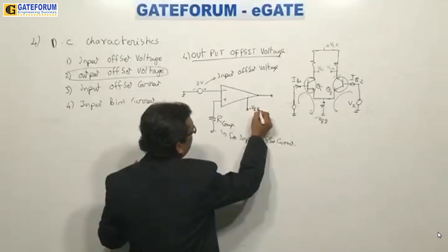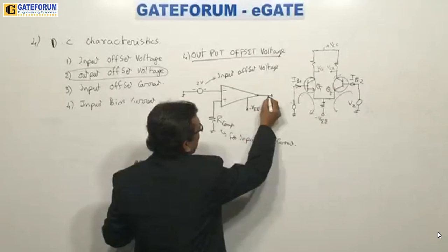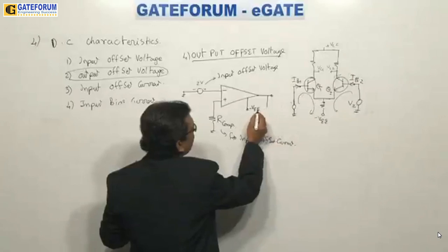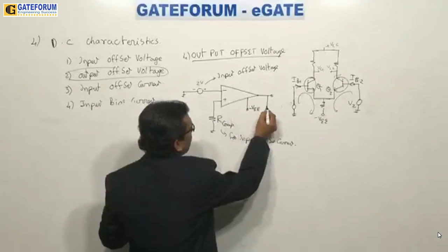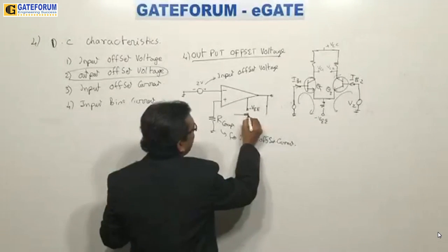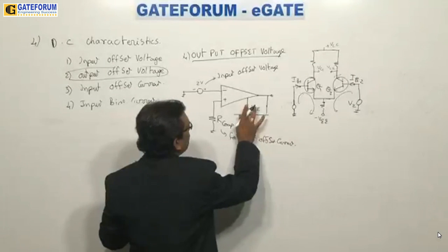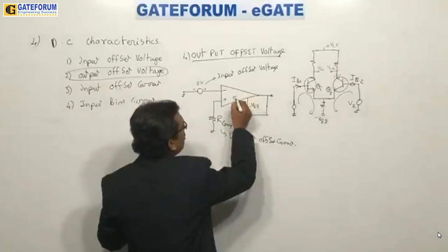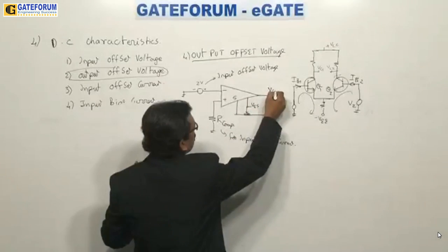The pin here is minus V supply, and I have this voltage like this. Now, using this power supply, I will put one potentiometer here like this, minus VEE, and connect this to pin 5, from the output.